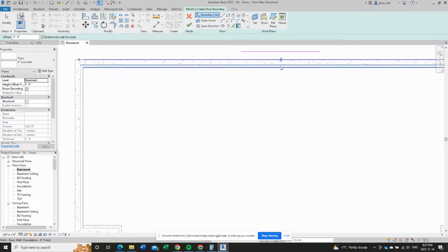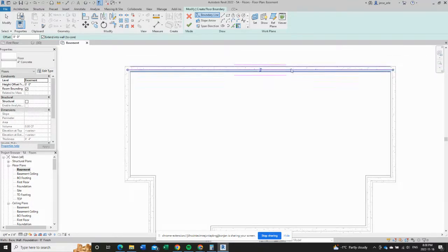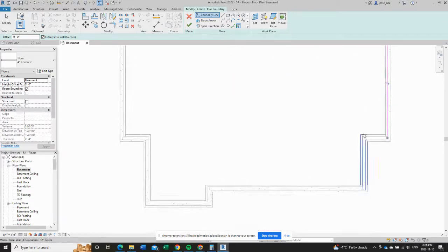Now here, if we look at our flip button, it is possible to put the floor right under the foundation wall, but in the sense of the basement, that wouldn't be right. The floor is only going to go up to the foundation wall. When we think about how the foundation is constructed, what is it resting on? It's actually resting on footings, so not on the concrete 4-inch floor. Once I've got my direction set here, I can just go around, follow the same process as we used for the main floor, and we're just selecting the walls to make a closed loop of a purple perimeter line.